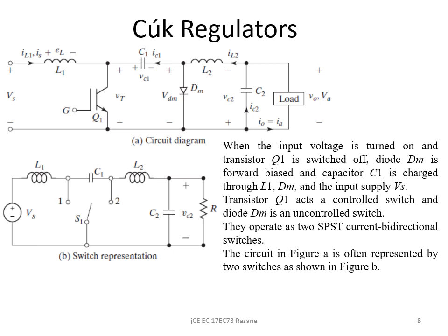If you see the circuit diagram of the Cuk regulator, there are two inductors, one at the input, one near the load end. There are capacitors C1 and C2, and this particular switch is in parallel with the supply. Basically we have two types of switches: one controlled by the gate, and another which is an uncontrolled switch. I can represent these two switches as two mechanical switches with mode 1 and mode 2 operation.